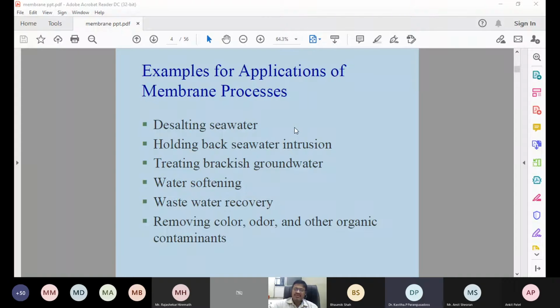Just guess, anyone. River water is there and the groundwater, in which will more dissolved solids be there? So it will be groundwater. Yes, it will be in groundwater. In groundwater, not river water. River water probably does not need, in the majority of cases, the removal of dissolved solids, unless it is near the saline zone. In the majority of cases, yes, river water does not need this.